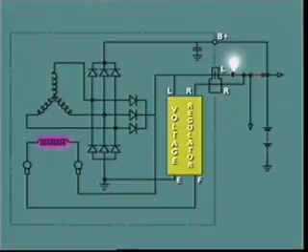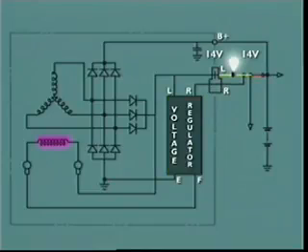The voltage regulator now takes over to control the field circuit current and maintain a preset regulated output voltage at the B positive terminal of approximately 14 volts. As the voltage on each side of the charge indicator lamp is now equal, there can be no current flow through the lamp and the lamp is extinguished.